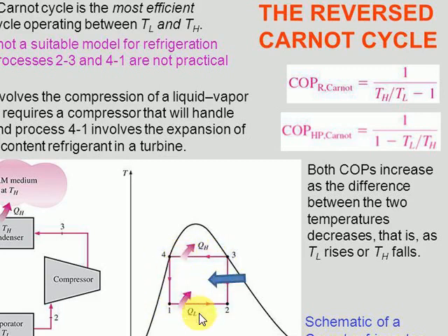Why are they not possible? Because you cannot stop the heating at a particular state. That is very difficult to control, because heating will continue till the saturated vapor. But to achieve this state and taking out the vapor at this state, supplying it to the compressor, is a very difficult task. And again, from 4 to 1, achieving the liquid plus vapor state is again difficult.